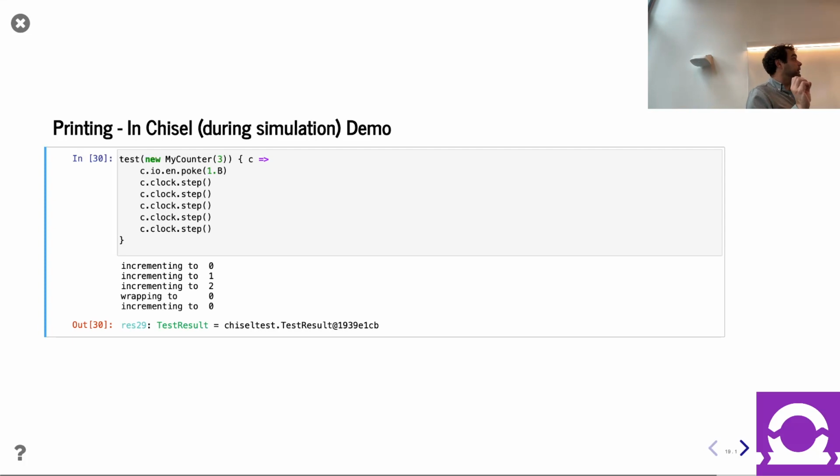The print statement is evaluated every clock cycle. So if you have combinational logic and you keep changing inputs to it, like for example with poke, and it's purely combinational logic, the outputs, if you do peek or expect, will change correctly. The printf will not be called. It's only called once per cycle, right?